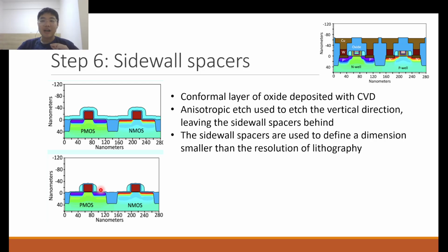So what is the purpose of these sidewall spacers? They are used to define a dimension smaller than the resolution of lithography. Remember, I told you that lithography is the primary way at which you create patterns on the wafer. But lithography, as you'll see in a future video, has a resolution limit.